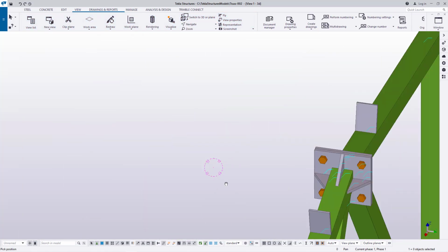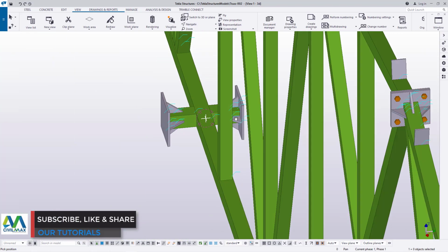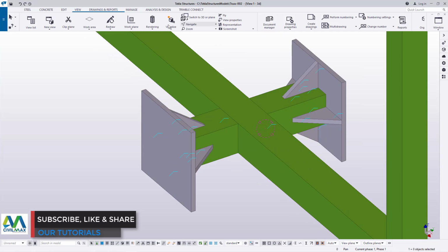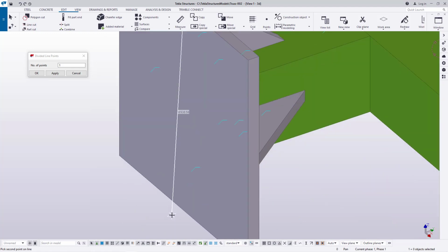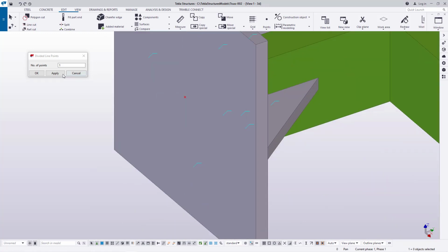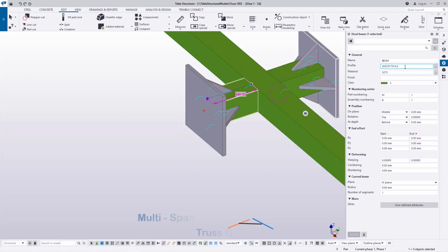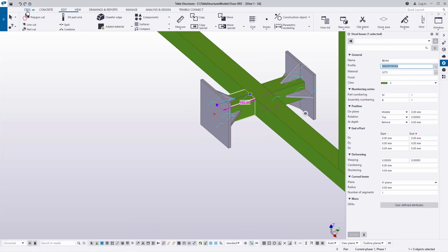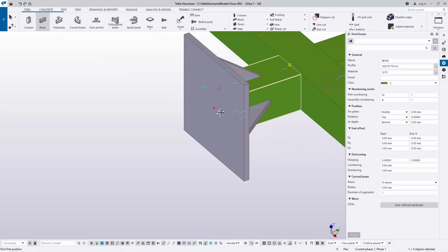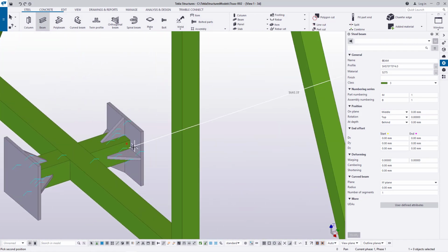So I'll come on the opposite direction here and try to get the midpoint of this stab for our tie beam. I'll come to Edit and come to Points here and snap on this spot and move all the way to this far end. I wanted just the midpoint here. So I'll double click on this member, because I want to use the same component, so I'll try to copy that. If I come to steel, I'll pick on the column and on the beam and snap on that spot and stretch all the way to this far end, and I'll snap right here.